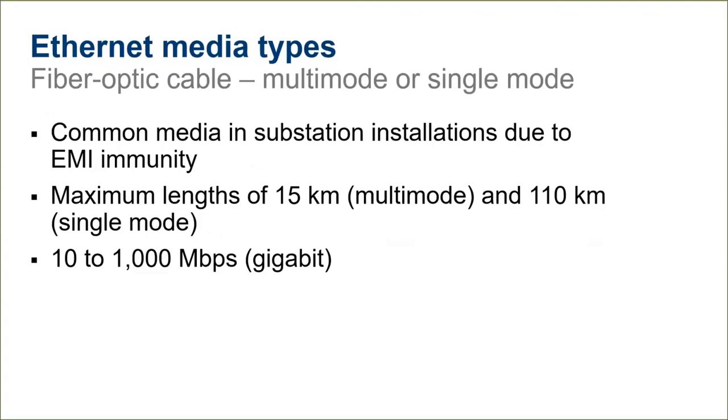So looking at the fiber optic side, kind of going all the way back, several fiber optic Ethernet standards exist, including some of the following. 10BASE-FL, or fiber optic link, was in widespread use years ago with 10 megabit per second Ethernet. And then there's the 100BASE-FX, or fast Ethernet. It's a modern standard for industrial Ethernet, so like IEDs or relays. And then there's the 1000BASE-SX and the 1000BASE-LX, which are multi-mode and single-mode fiber at gigabit speeds, typically used for uplink between fiber Ethernet devices.